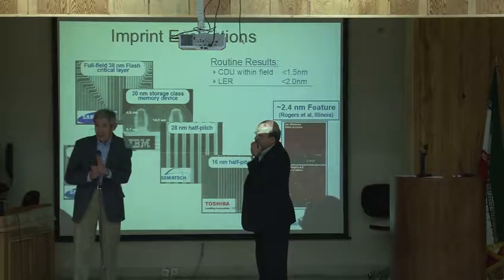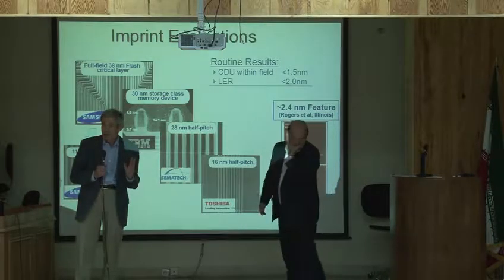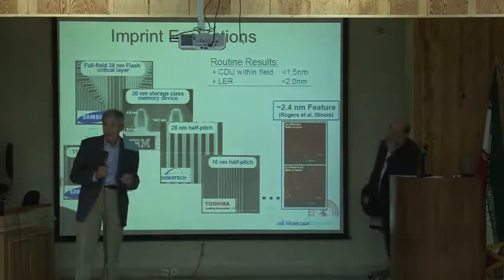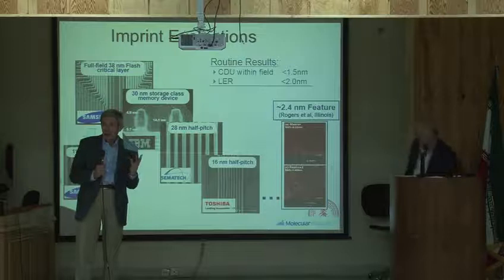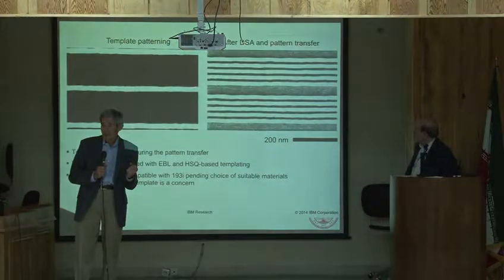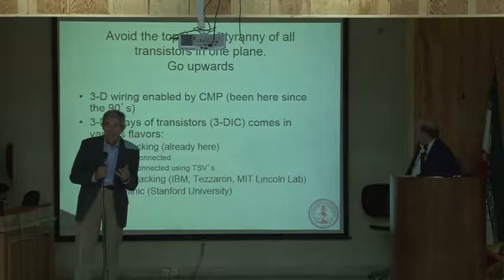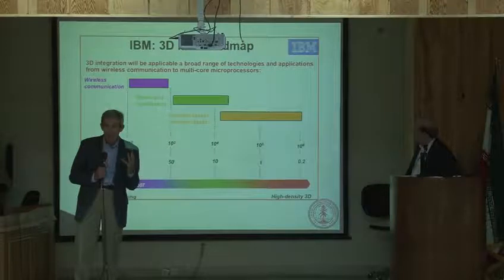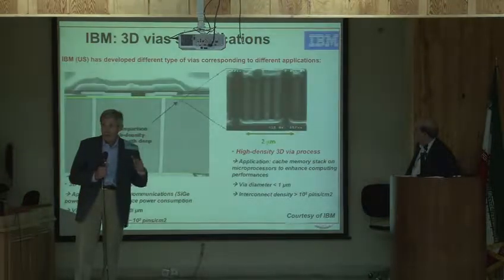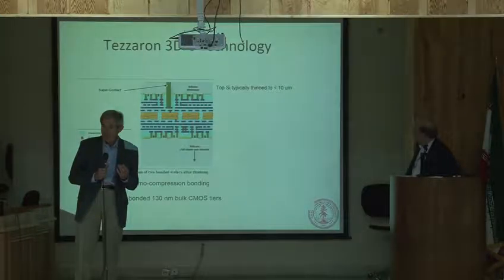If I think I understand the question, I'll give my answer. I picked very crude models. And as we discussed, if you make the vias very fine, then the power distribution becomes difficult. There is a problem with the L di/dt noise. Do you know what is meant by that? Okay, yeah. When you suddenly switch, the whole power and ground levels might change. So you need to have fairly thick vias for power delivery. So it limits the partitioning granularity of the design.